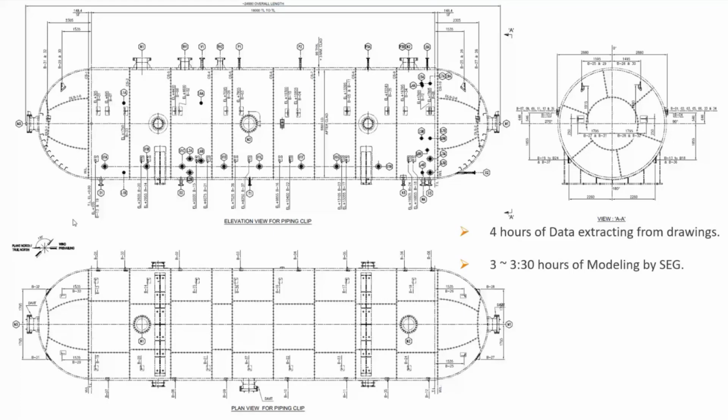As discussed for the head, for example, this hemispherical head, you will find 4 types of hemispherical heads. Which type suits your case? If you would like to make a hemispherical head with a negative straight flange, don't go and select an ellipsoidal head. You should select the correct, suitable type for your case. If you would like to make a forged hub with lip as a nozzle, don't go and select a nozzle from pipe or a nozzle from plate.